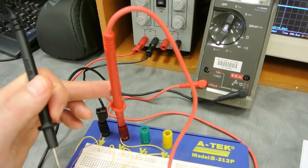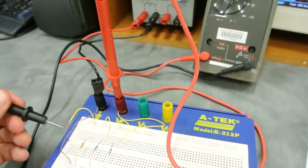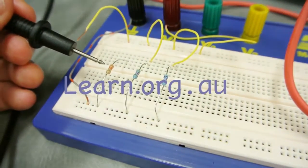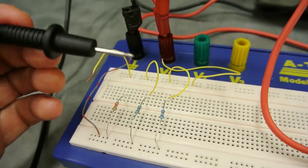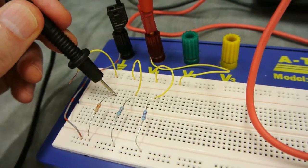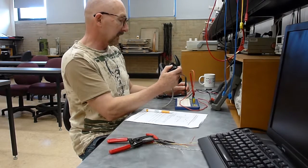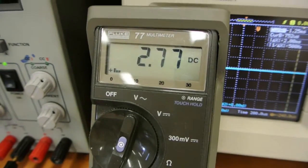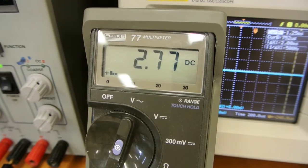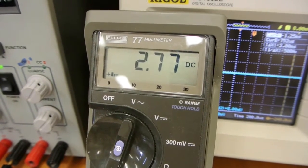I've put the positive lead from the milliamp meter back onto the 9 volt positive terminal. I have the 3.3k resistor disconnected from the network, and now I'll use the negative lead on the current meter directly onto that 3.3k resistor. So all the current is coming from the 9 volt supply and going through the current meter. The current meter tells me I have 2.77 milliamps DC current flowing through that resistor. So I'll write that down into my table.